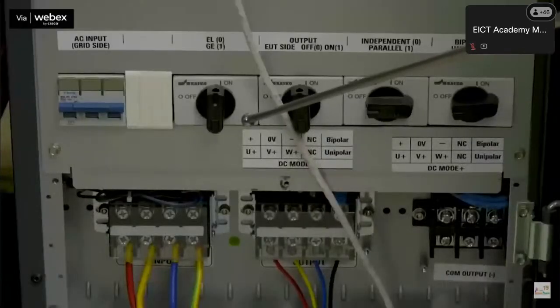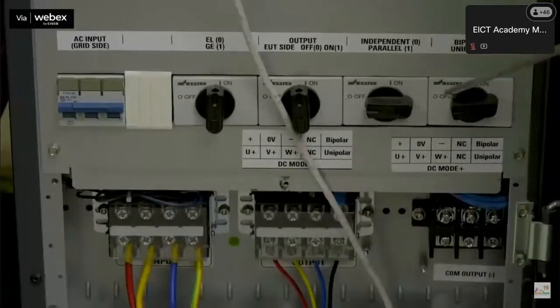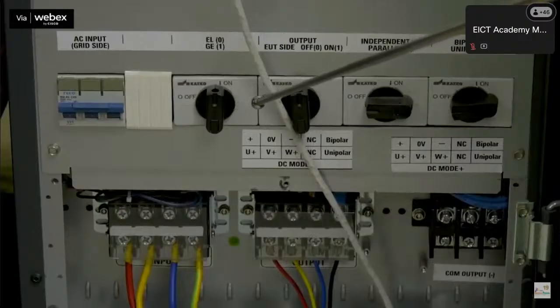If the working mode switch is at AC mode, the equipment can be used as an electronic load and grid emulator. Similarly, if the working mode switch is at DC, the equipment can be used as a DC source, battery emulator, PV emulator, as well as programmable DC loads. For the various functions of this equipment, the switches are numbered from 1 to 4, from left to right. Let us see how to configure various functions of this device.